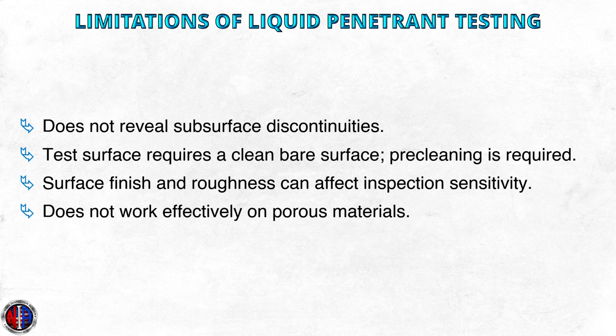Limitations of liquid penetrant testing. It does not reveal subsurface discontinuities. Discontinuities must be open to the surface. The test surface requires a clean, bare surface. Pre-cleaning is required and is incredibly important. Surface finish and roughness can affect inspection sensitivity. It does not work effectively on porous materials.